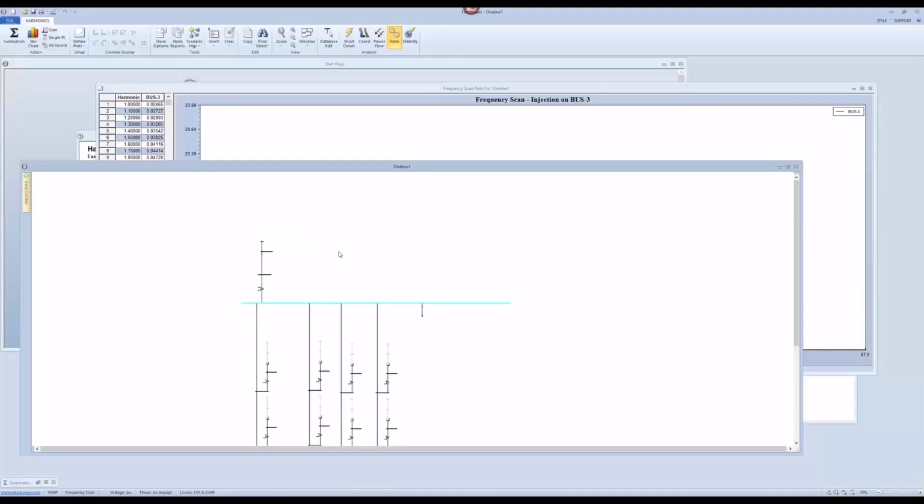There is no radial connection requirement for EasyPower harmonics. You can feel free to add looped networks in the transmission and then add different places with different harmonic injections from different power plants and aggregate them together into a combined model and study, which is very neat, but it's very comprehensive as well. So capability, yes, just be careful about the penetration level of your harmonic sources along your system and model the system size properly, right?